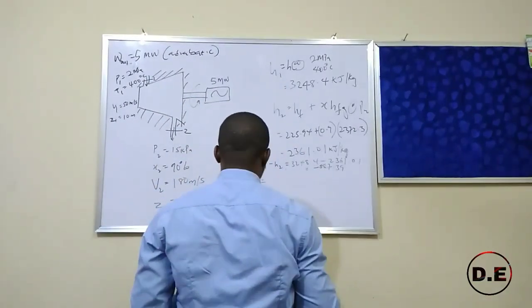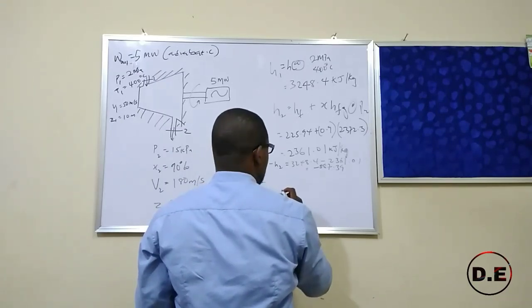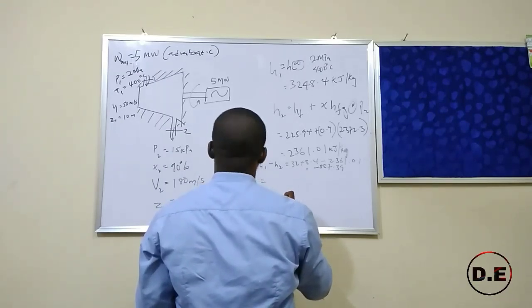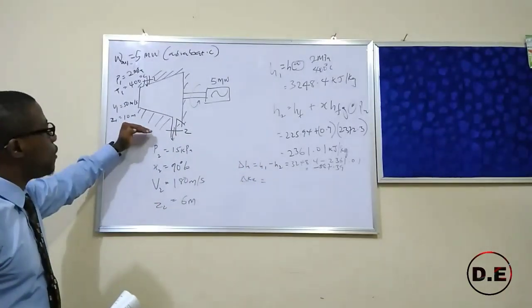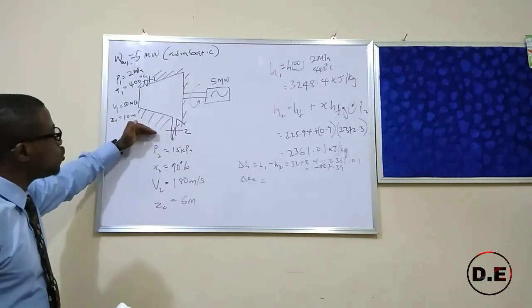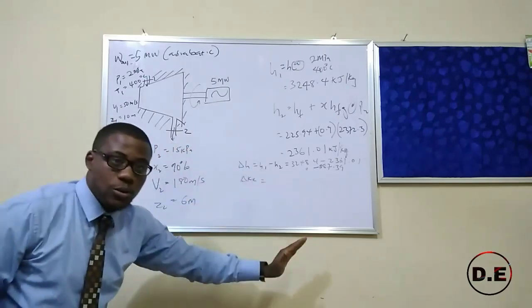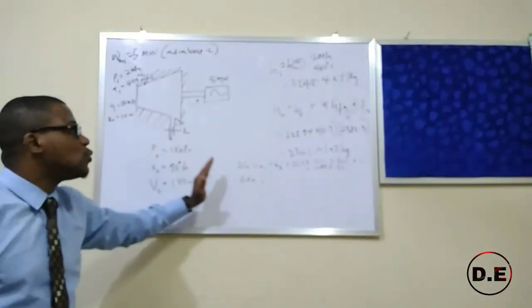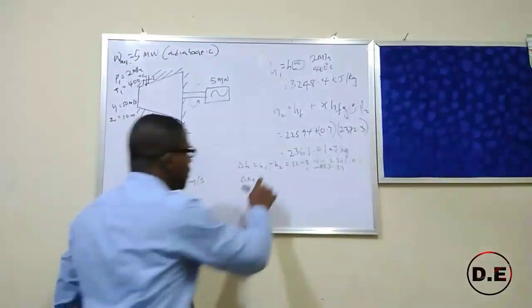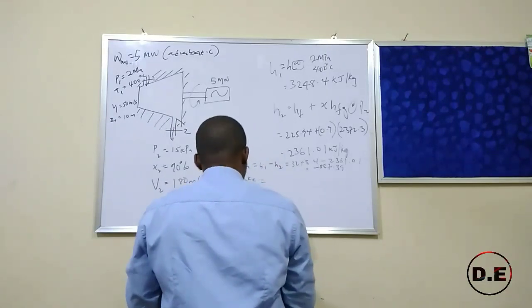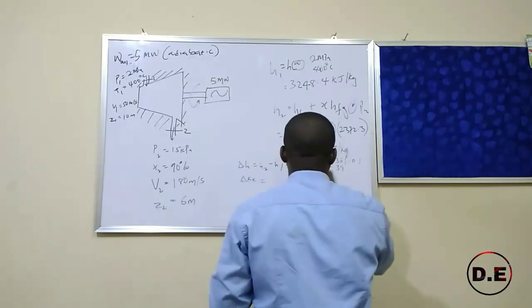Next is to find the difference in kinetic energy, KE, and that is going to be the difference of squares of velocity. Now let me point this out: if we start by saying H1 minus H2, we have to use that convention throughout. So I'm going to change what we got initially for the enthalpy to H2 minus H1 so that we can continue with that convention.